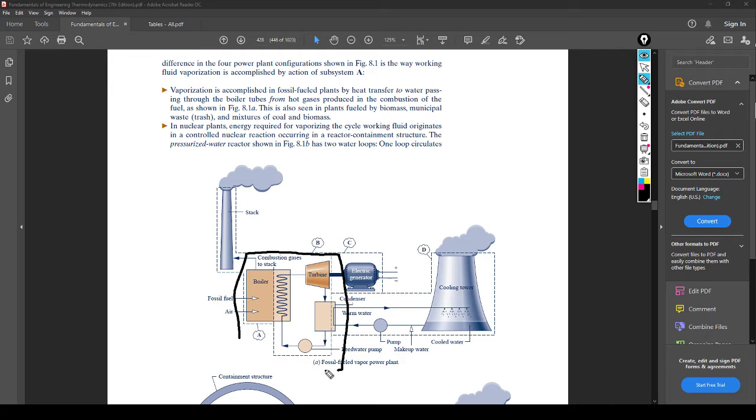Again, I'm going to outline it. This is the Rankine cycle. And what they said in those two parts, the first and second laws of thermodynamics, in respect to this, they only mentioned the corollaries that mattered. Essentially what it's saying is that if this cycle exists right here, the highest amount of energy we could ever get out of this cycle is right here. Essentially, it's Qn, right? Because this is what's powering the cycle. This is what's heating up.